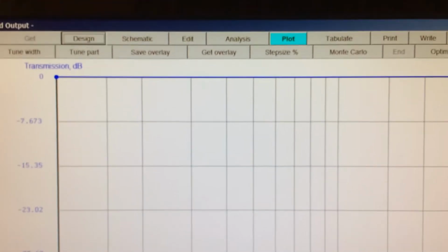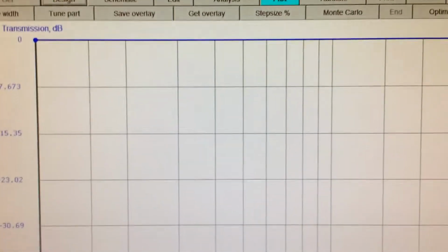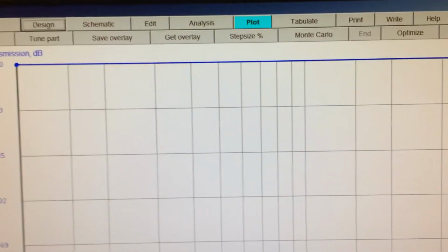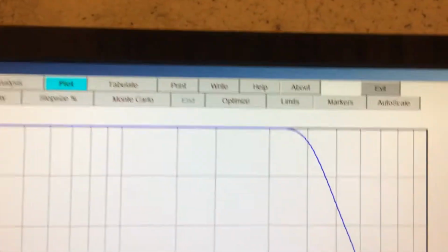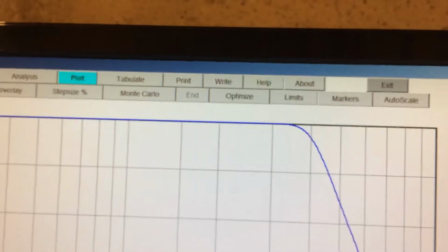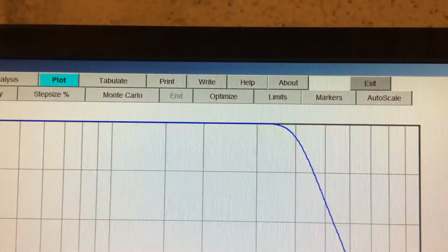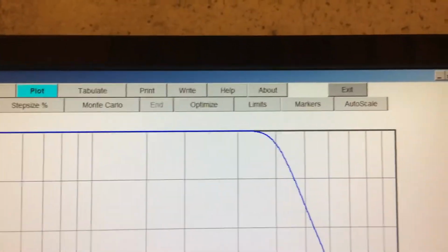So the 2nd harmonic is 60 megahertz, the 3rd harmonic is 90 megahertz, the 4th harmonic is 120 megahertz, right? Usually, by the time you get to the 5th or 6th harmonic, it's not a problem. It's going to be well below the fundamental frequency, and we'll look at that on the spectrum analyzer in part 2.